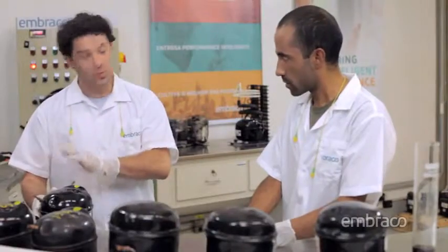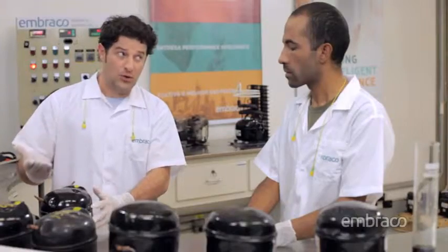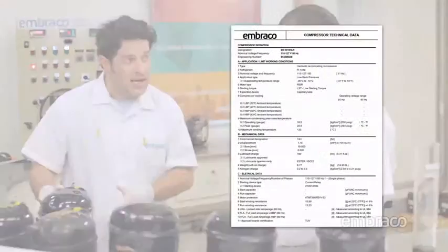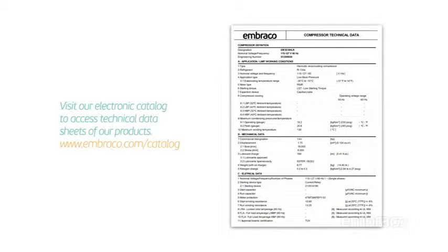Look for a dented tube or cracked insulation, dirt around the condenser in order to identify if the problem really is in the compressor. And also, before removing the compressor, we must check the electrical components. Remember the video about changing compressors, right? Oh, right. So how do we check if the compressor isn't defective? First, we check the ohmic resistance of the windings and compare it with the information on the datasheet.